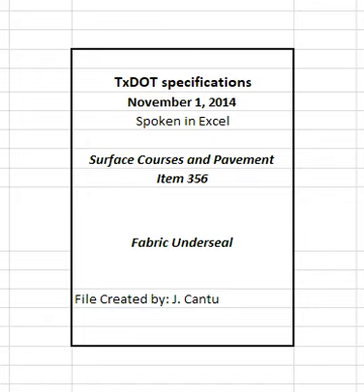5 Measurement. 5.1 Longitudinal, full width underseal. 5.1.1 Asphalt binder. Asphalt binder will be measured as follows. 5.1.1.1 Volume. Volume measurements will be made at the point of application on the road as gallons used at the application temperature, as directed, in the accepted fabric underseal. 5.1.1.2 Weight. Weight measurements will be by the ton in accordance with item 520, weighing and measuring equipment. At the end of the project, deduct any remaining material from quantities delivered to determine pay quantities.